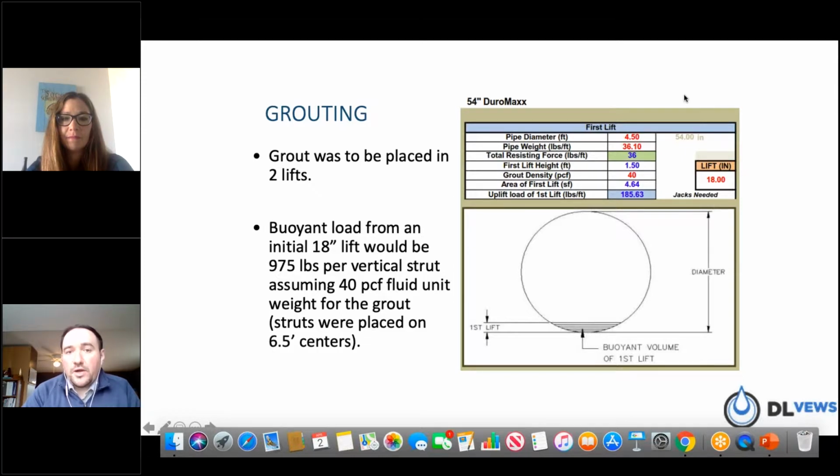Putting grout ports inside liner pipes, as a general statement, does not damage or risk damaging the structural design of your liner pipe. But it's always worth checking with any manufacturer: how many should I put, how often should I put them? That's going to be a two-way conversation between you as the installer or designer and the pipe manufacturer. Because maybe you say, I want 5 ports at every 20 feet, or I don't want any ports because I don't want any holes in my pipe. That's a quality concern, and I would understand why an owner might say that.